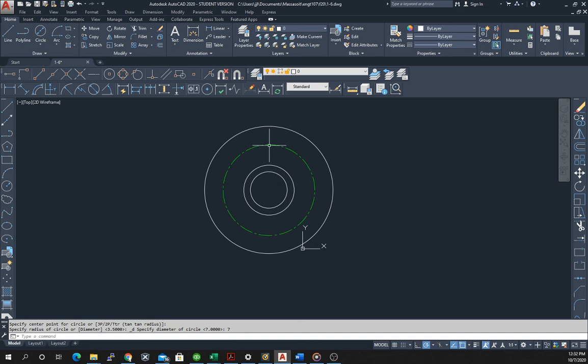Now, the question you might be asking, why is this green and in the center layer? And the reason for that is that it's not actually a machine part of the drawing. It is what is called a bolt circle. And it's put in the drawing only to give a definition of where those 3 small circles in the drawing are going.